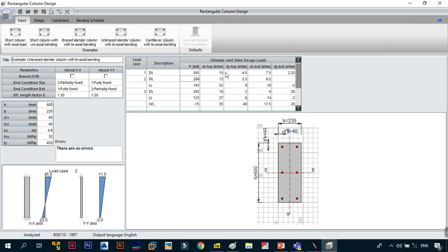And one thing you just want to show is that use the same sign for the top and the bottom, because otherwise once you start using different signs, you are counteracting your moments. And just remember, positive is an anti-clockwise moment and negative means it's a clockwise moment.